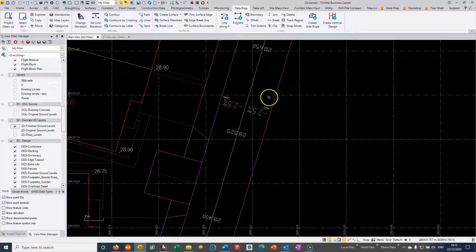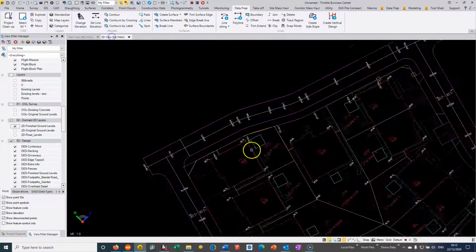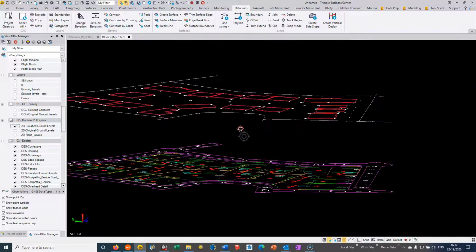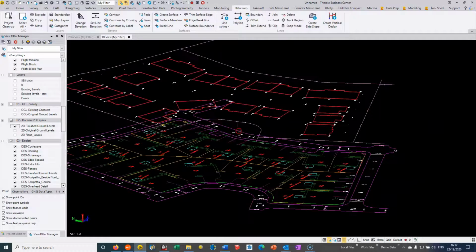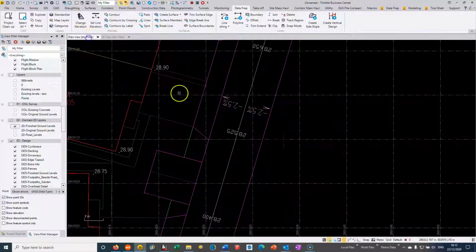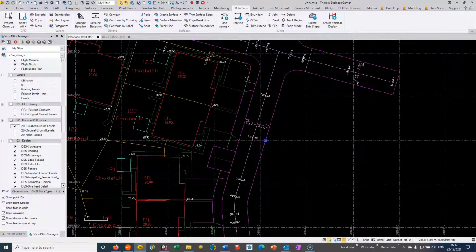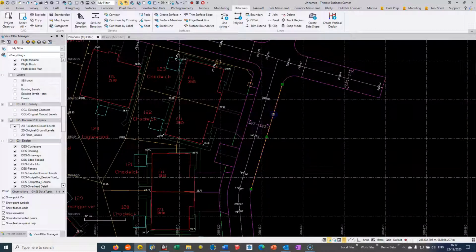So what I want to do is, just remind ourselves of the situation. We've got elevated center lines. Now we want the channels to be elevated up to the center lines. So to do that, I'm going to select the channels. Now you can see here that basically what we have is individual entities. So it's actually useful to be able to connect these up.